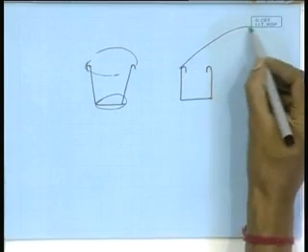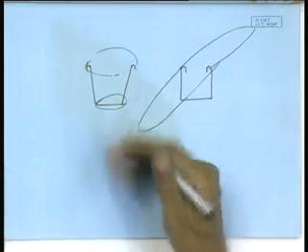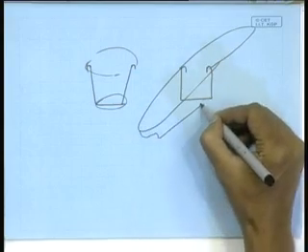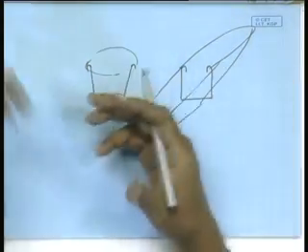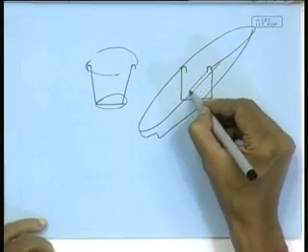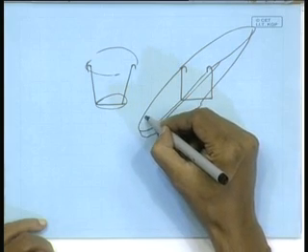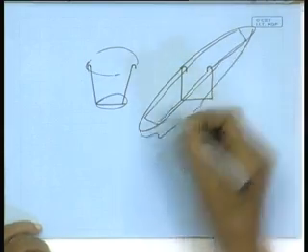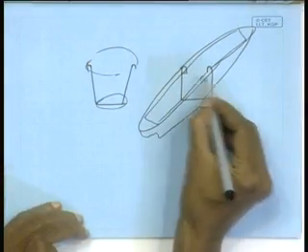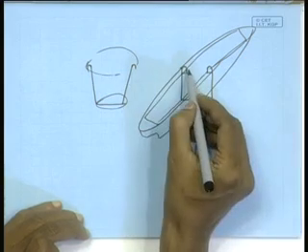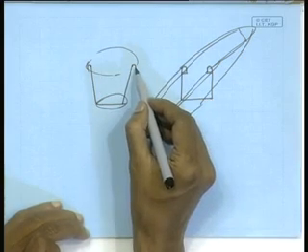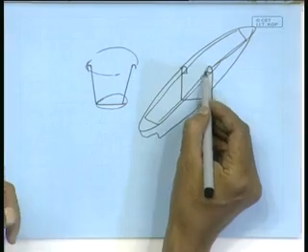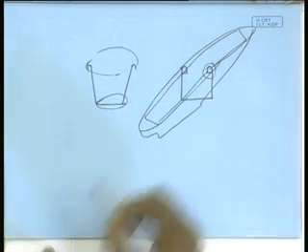But in this case, it's a much longer object. So, this rigidity is required all round. What is happening? This box girder is extending all through. Like in the case of the tumbler, just by turning the edge, I could achieve the required stiffness. Now, here obviously stiffness required is much higher. So, I am not only turning the edge, making this heavily constructed.